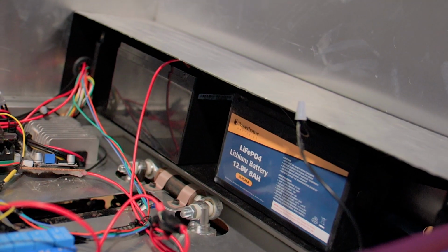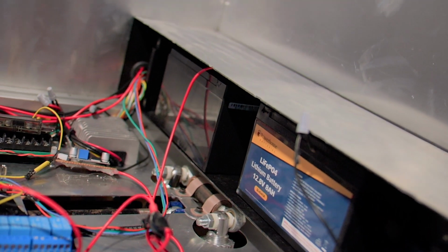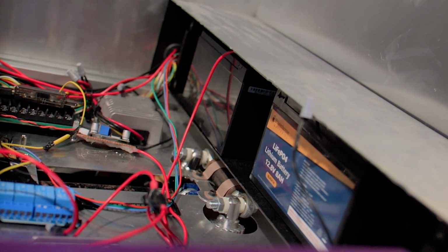Powering the ADR is a relatively simple but safe and reliable power system. Powering it all are 3 LiFePO4 battery packs put in series, which provide 36 volts with 8 amp hour capacity, which is enough to last over 4 hours under conservative assumptions.